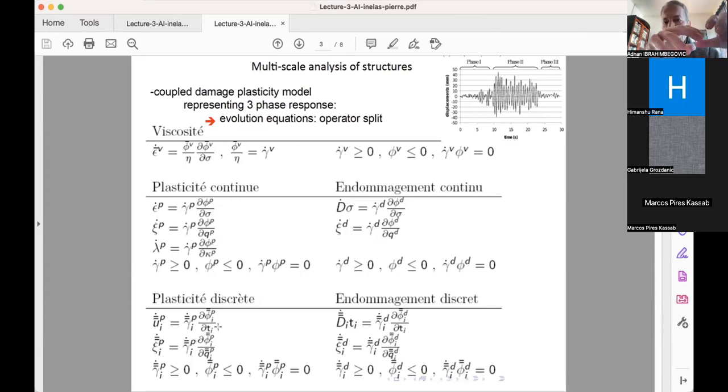And then you can work out the modal analysis, which is typical of linear analysis. Having chosen a damping matrix to be a linear combination of stiffness and mass, you can obtain your eigenvectors that are the same as undamped vibrations. That doesn't change. And then you can write your modal equation, which features now a damping coefficient, psi, which is defined from the mass and stiffness matrix, a contribution coming from the mass and from the stiffness.